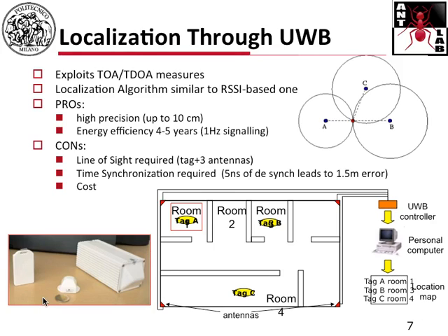Why is it more precise? Because if you have a synchronous network, the signal you're using to localize, the time of arrival, is much less noisy than received signal strength or received signal indicator, which, as we will see, is more noisy due to interference and such.